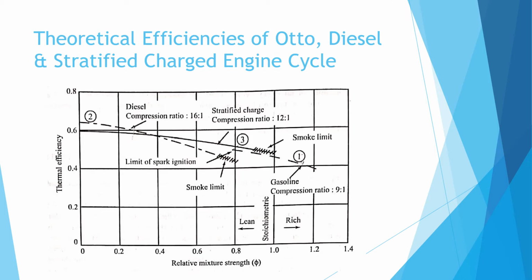So therefore there are three distinct advantages of using charge stratification, that is no throttling losses, less prone to knock due to the reduced residence time under high pressure and temperature condition, and multi-fuel capability.